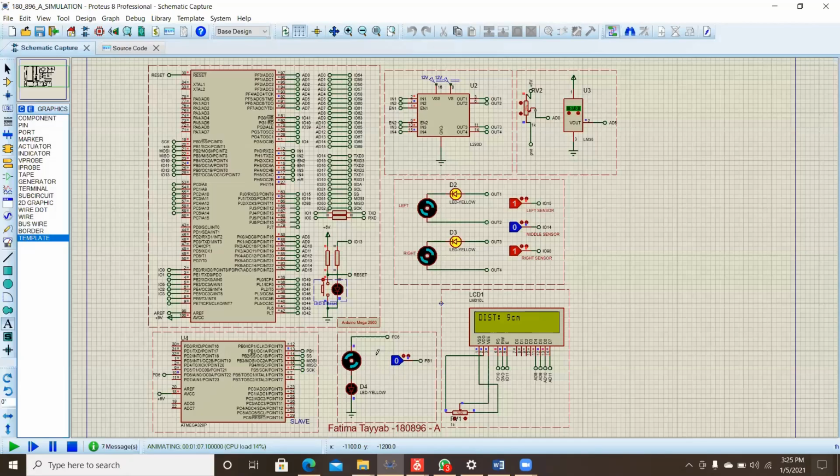When it is 0, the PWM of OCR0 is equal to 30. That means its duty cycle is 30, and there is a small blink in the LED. And when it is 1, the motor will rotate faster, and there is a larger blink.